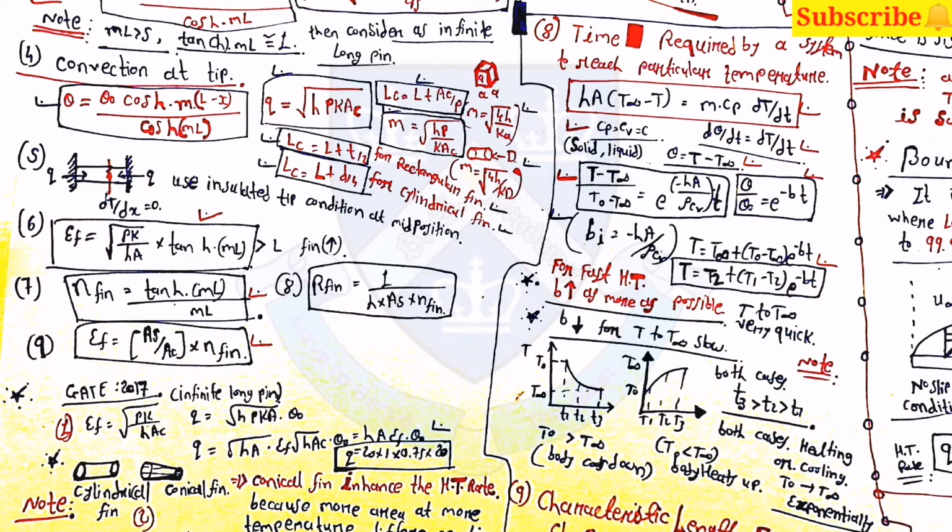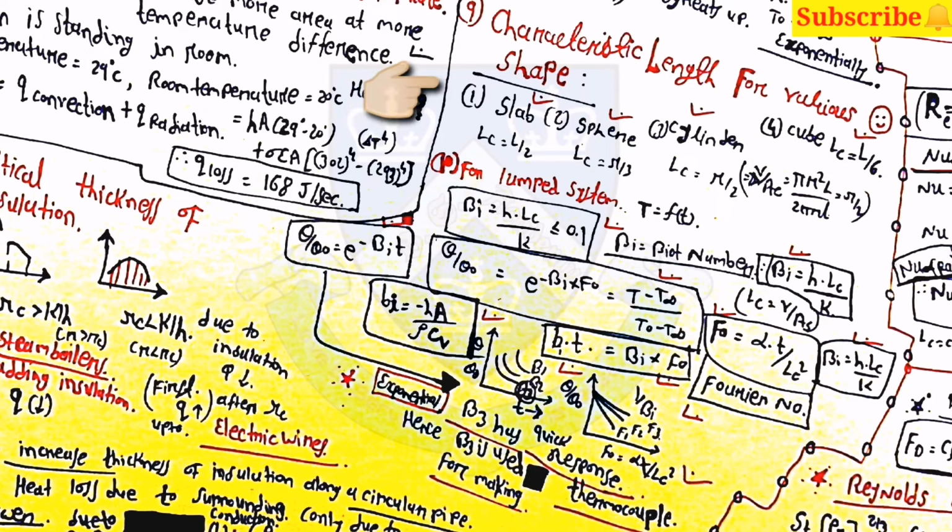The body cools down, and the body heats up; in both cases T3 is greater than T2 greater than T1. Then the characteristic length for various shapes. Here for a slab Lc is equal to L by 2, for a sphere Lc is equal to R by 3, for a cylinder Lc is equal to R by 2, and for a cube Lc is equal to L by 6.